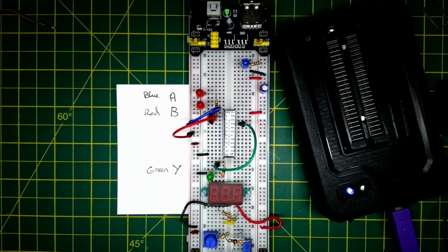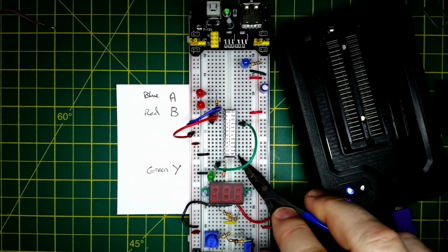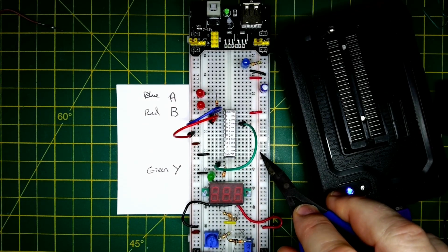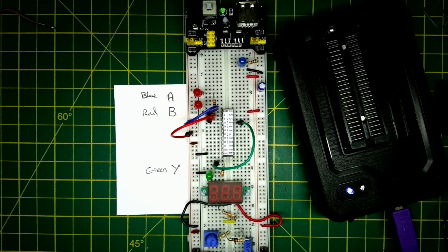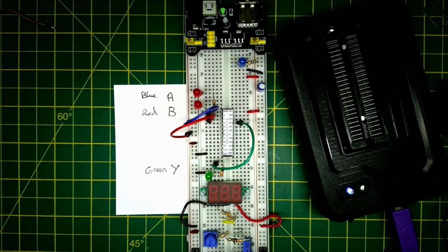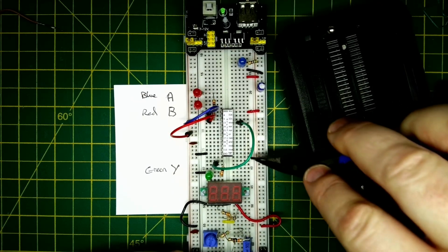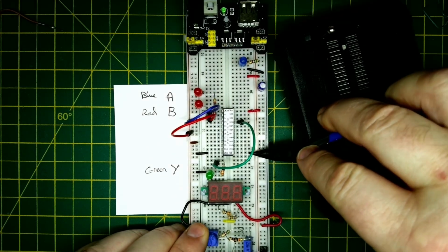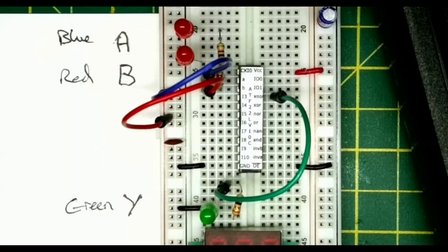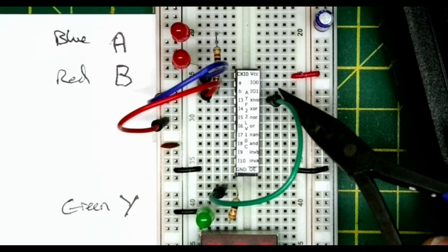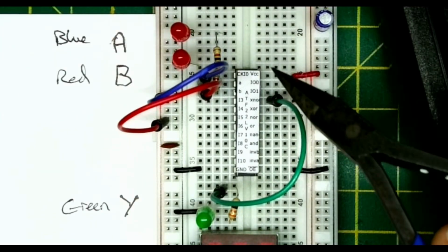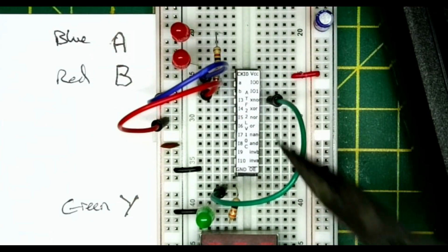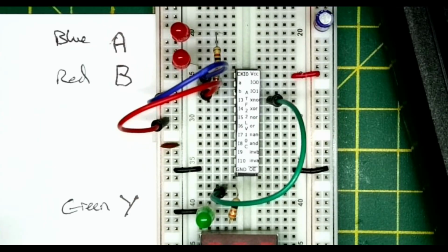Now what we do need to remember is we have the output enable there. Now by default we know the output enable is likely to default to high, so if we don't actually put a link in there, then we may not actually see anything. So we need to put the output enable to ground there. So we can see that our output is in the exclusive NOR, A and B are on pins 2 and 3, and so we'll now try that.